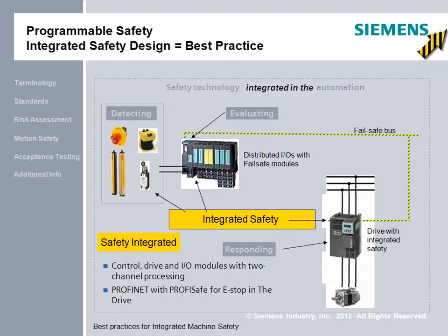The response mechanism, or in this case the actuator or servo, is now a safety-rated drive system. You'll notice that there are no contactors in series with the drive system. Recent changes in the U.S. standards, NFPA 79 in particular, in the last several years, have allowed the use of safety-rated drive systems in this manner to perform this function. No longer do we need a contactor in the three-phase supply system to reach the desired level of functional safety.